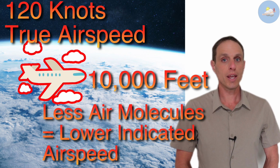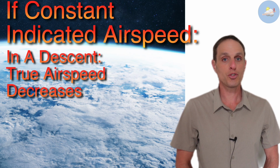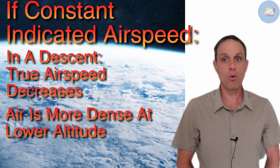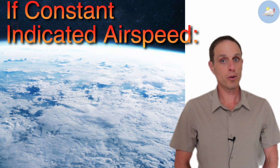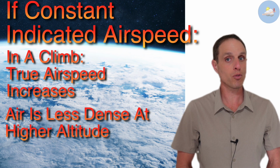Here's why it's so important for controllers. If a plane is flying at a constant indicated airspeed, say 100 knots, and it descends, its true airspeed will actually decrease. Why? Because the air gets more dense as you descend, so it doesn't need to fly as fast to keep the same number of air molecules hitting it. The opposite is also true. If a plane climbs at a constant indicated airspeed, its true airspeed will increase. This is a crucial concept for what comes next.